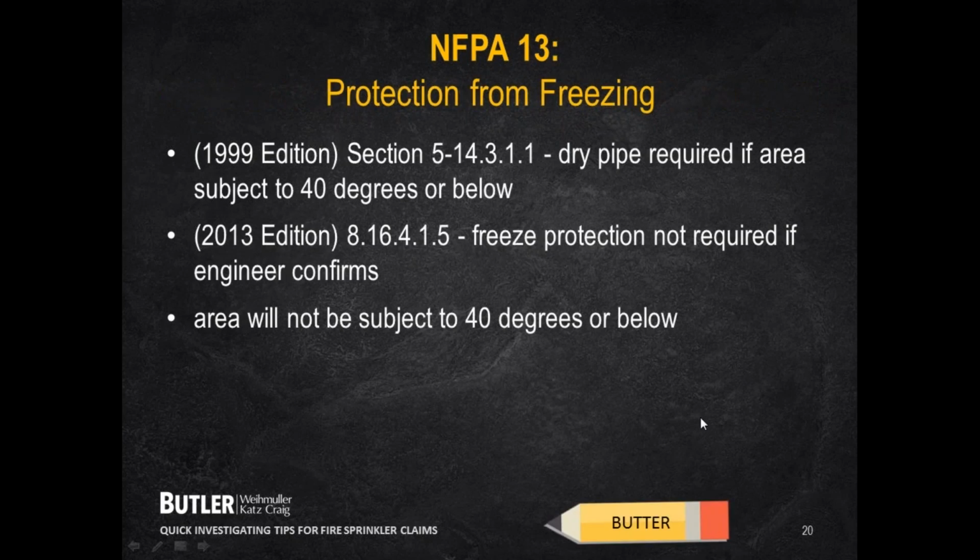So in the NFPA 13, the protection from freezing, this is where you'll get a lot of information from your fire sprinkler engineers, and you've heard us talk about it over and over again today. It's the importance of a dry pipe, which is not supposed to have water in it. And a dry pipe is required if an area is subject to 40 degrees or below. And that is the 1999 edition.